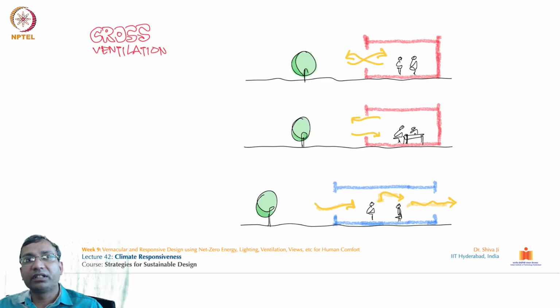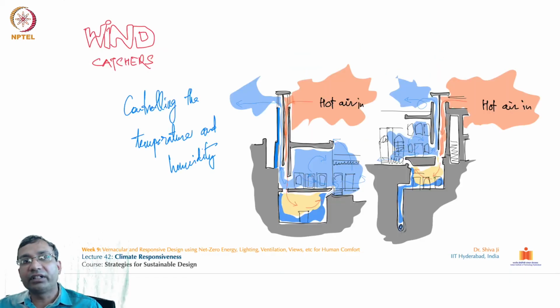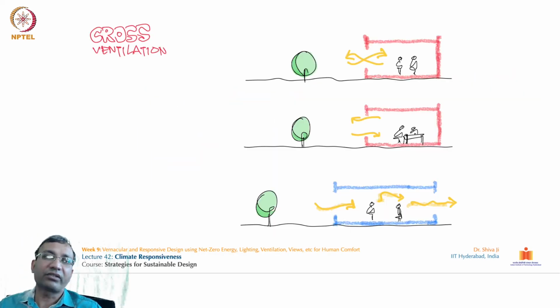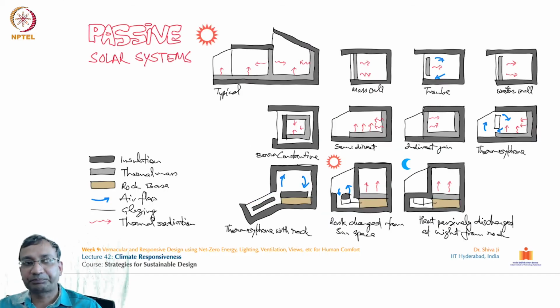Further continuing our previous discussion, in the cross section also we can plan our openings in such a way, like the one we saw in this wind tunnel, wind breeze wall, in this cross section. So similarly, even if we are not going to have very tall structures, we can plan the openings, the cross section of these openings, the length and width of these openings, we can make them vary, and depending upon that we can control the passage of wind through the premises.